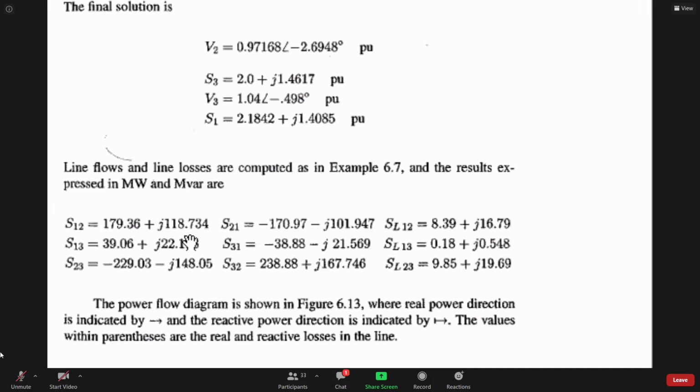Any suggestion? Sir, we know S1 and S2 individually, so we can subtract them from one another. Something like that. Where have you got S2? Sir, in the above iterations. S1 is the complex power. S2 is not given, right? S3 is there. So S12 you have to find actually using V I conjugate, right? Using that V I conjugate.